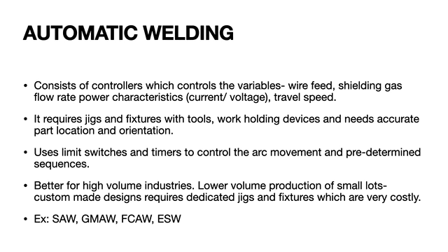There would be some wheel associated with it which will be electronically controlled by the controller, and then the power source will have certain connections with the controller so that the required current and voltage can be adjusted as per the requirement. The wire feed is not a very complex thing. Even in the semi-automatic process we use that wire feed. It basically depends on the simple volt-current carrier. I think I had discussed this in class 1 or 2. And then the shielding gas flow rate can be adjusted with a small actuator.